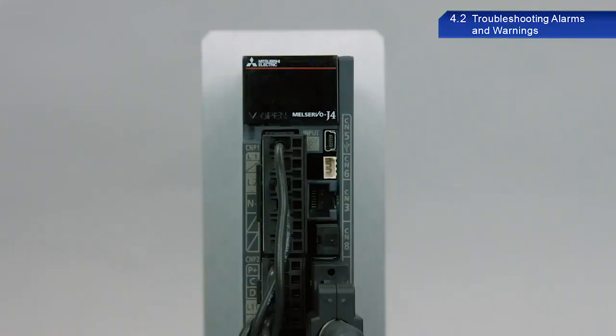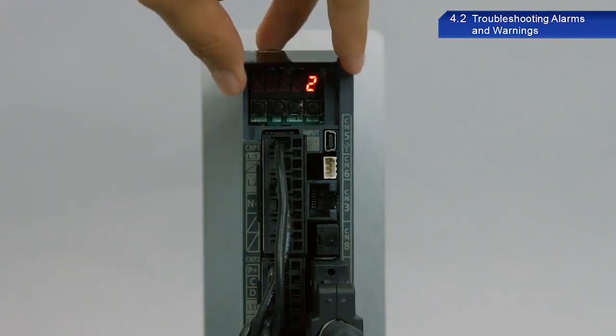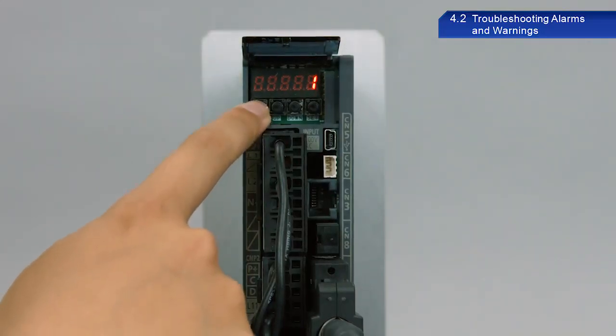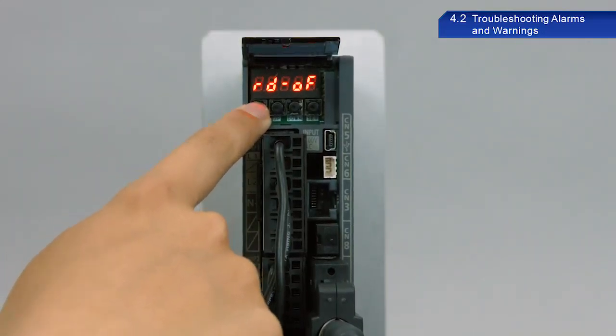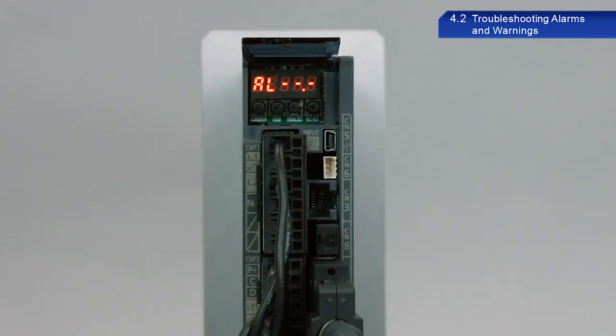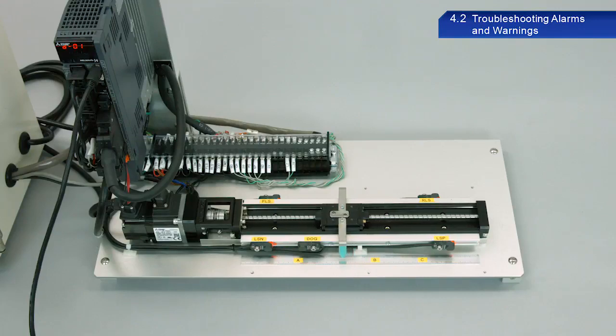Turn on the power to the servo amplifier and make sure the alarm has been cleared. Use jog operation to return to the origin position of the workpiece.